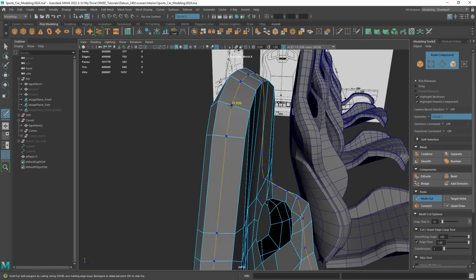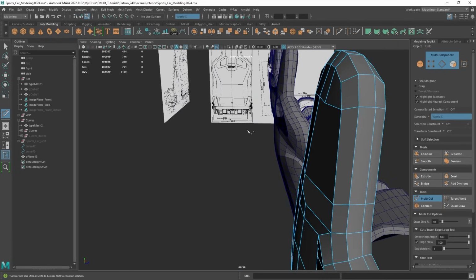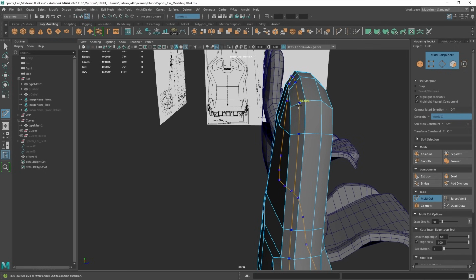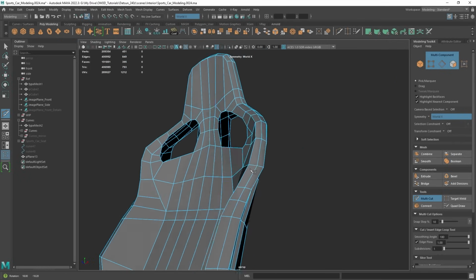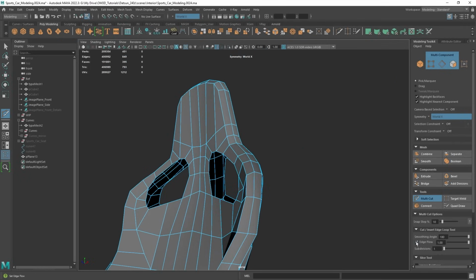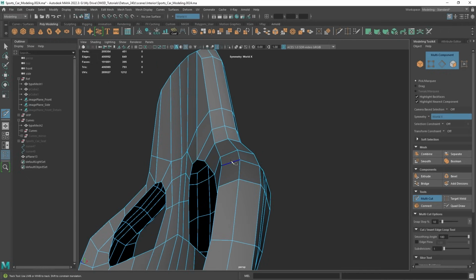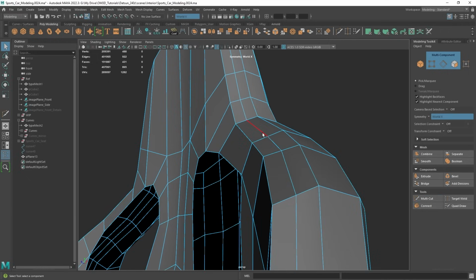And what this does, so if I hold control, you can see I can start to highlight the edge where I want it. And then if you just middle mouse click, it'll put it right in the middle, and you can start to see this gives you a nice way of adding good curvature to your model without having to manually do it. And now, if you do want to manually do it, you can turn off edge flow here if you want a little bit more control. And I can, again, maybe control middle mouse, put that right in the middle.